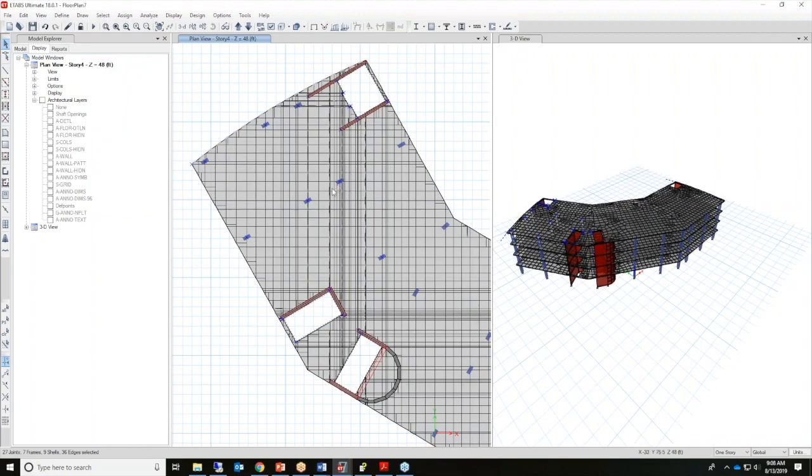All the lines are very close together, and the meshing looks very messy and splotchy. For this specific example, I'm really pushing the point of using the general mesh type option. In the next examples, we'll talk about rectangular meshes having a better use and a better option for those types of models. Okay, we'll leave this one open and we'll come back to this.